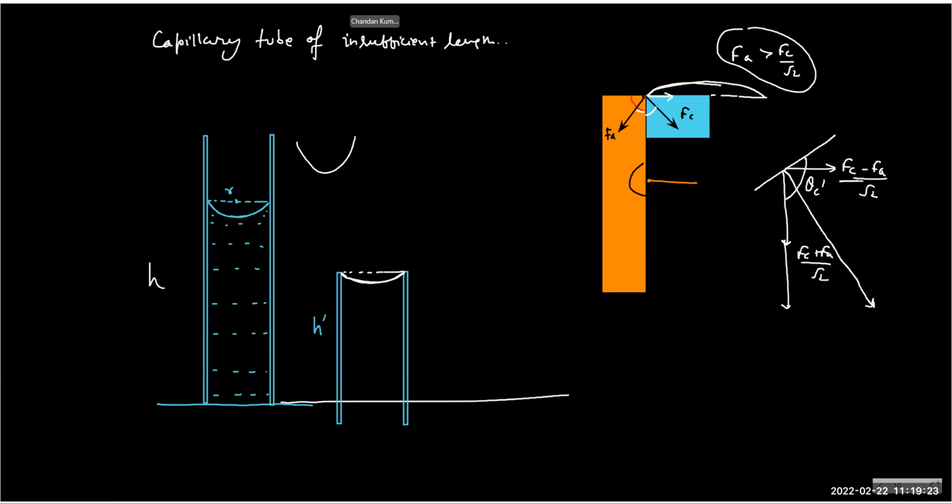So now, if I remove the atmospheric pressure, what will happen? So it will spill out. Now, does gravity depend on atmospheric pressure? So if you look at the formula of capillarity, do we have dependence on atmospheric pressure? No. We have dependence on the gravity, not on atmospheric pressure. Yes, sir. So that's why the confusion is because of the formula.